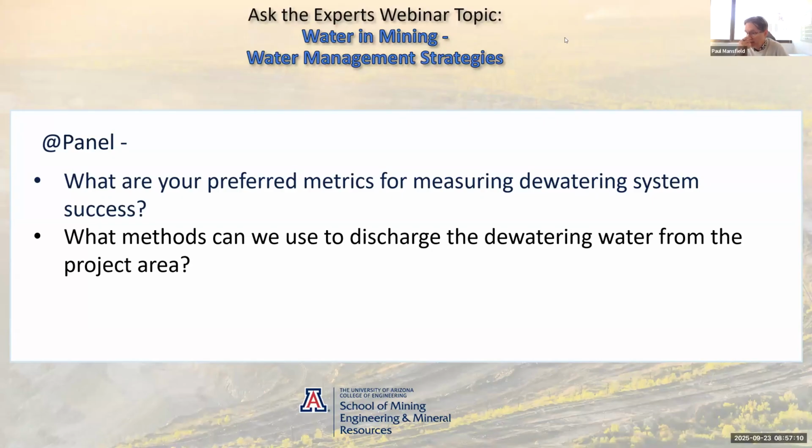Well, it all goes hand in hand with the slope stability. So hydrogeologists and geotechnical engineers have to talk to each other when you define your targets for depressurization and dewatering systems. They should never be defined just based on the hydrogeology. They need to be defined based on the rock quality and the areas of instability in and around the pit. So it always has to go hand in hand.